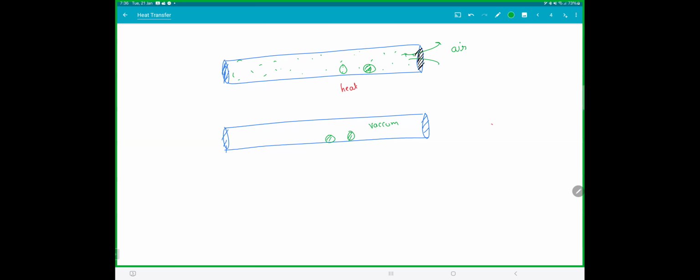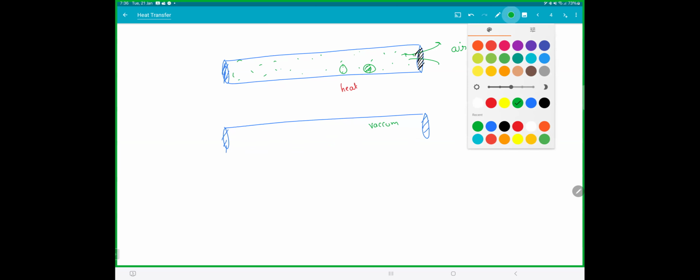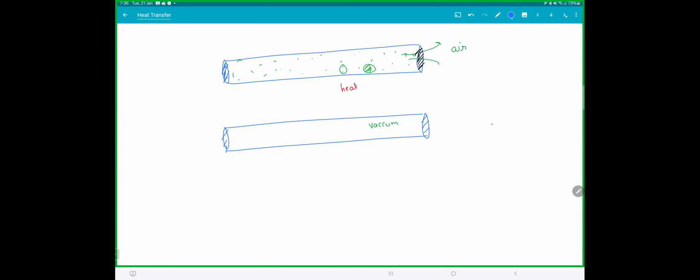Now see what happens. Now inside has become vacuum. Now there is some water droplet here. Now the moment you give heat, this water will suddenly vaporize. In chemistry, if you studied, right, what is boiling point? If you decrease the pressure outside, water boils pretty easily. That is the reason higher the altitude, lesser the boiling point. Now inside it is almost vacuum. There is no pressure. The moment you give little heat, it will suddenly vaporize and you'll get steam.